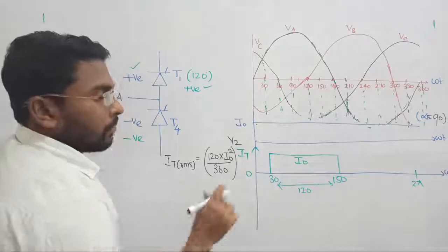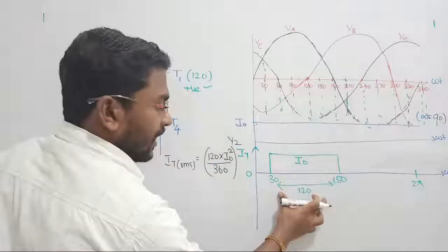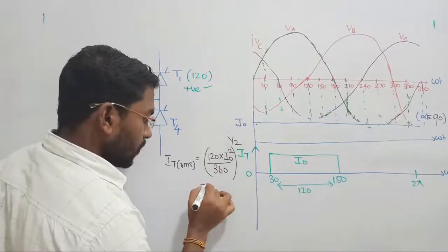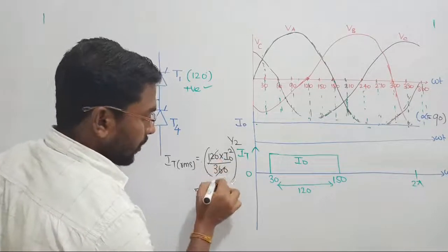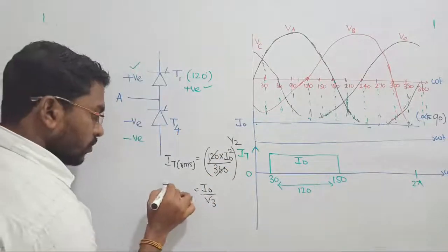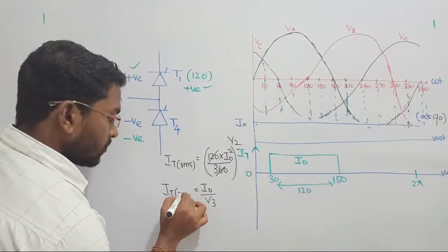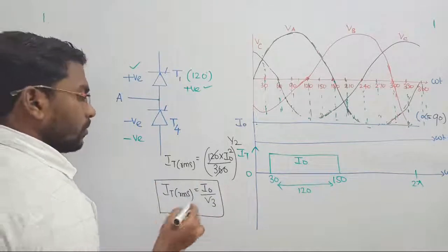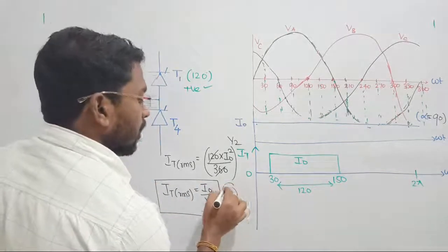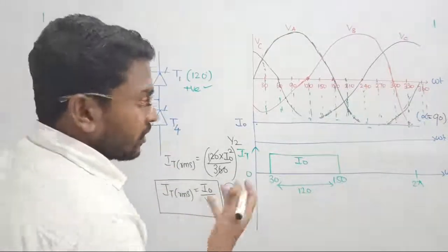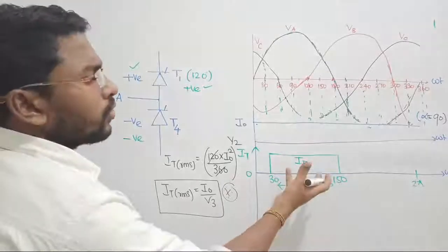That is all. Only square the magnitude, the same time period, the same whole time period, but keep them all under root such that I naught comes out. If you cancel this, it will become root 3 because it is lying under root. See there? So the RMS value of the thyristor current becomes simply output current by root 3. Very important formula. It might look chilly, but while reading the question you will forget these things. Even if you forget, no problem. We know how to develop it.